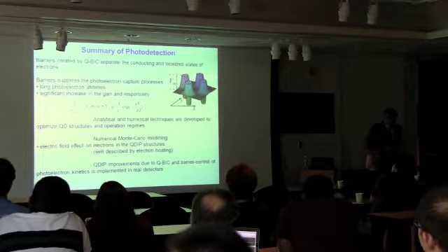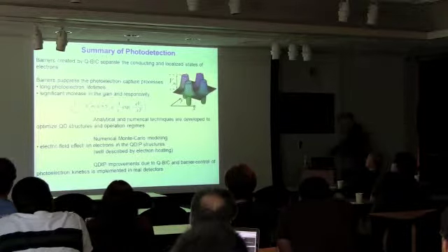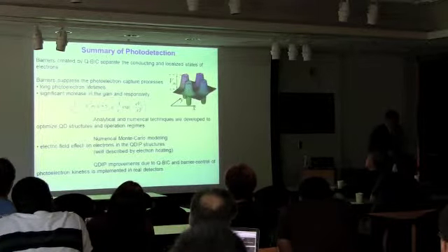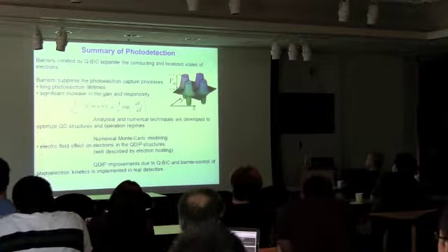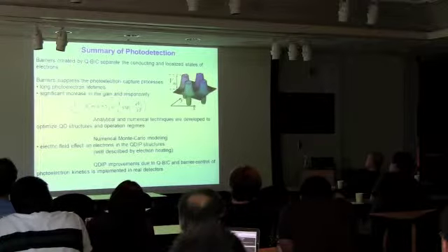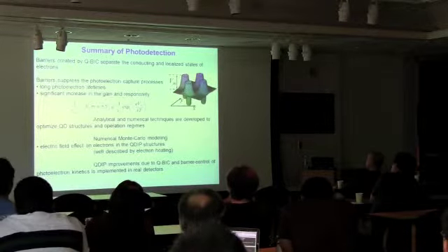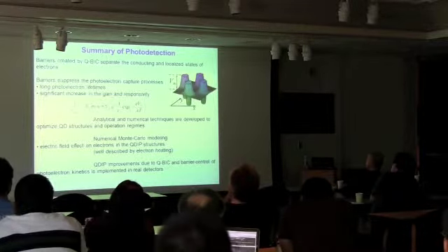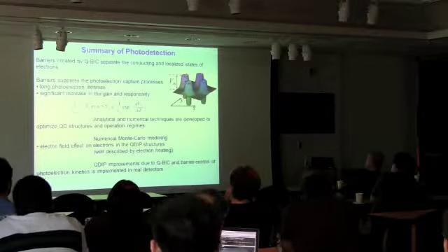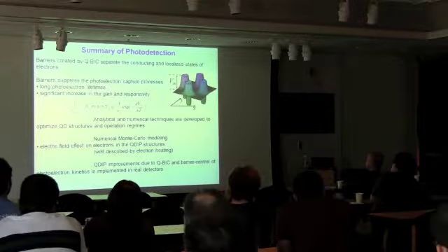And now I put a summary of the first part, where we had one type of carriers, only electrons, because it was a photodetector. As you see here, by creating the repulsive potential of the dots, we exponentially increase the lifetime of the carriers when they are out of the dots, and by that we increase the responsivity of the photodetector, because now the gain becomes huge, and in some examples we have gains that reach 1000.